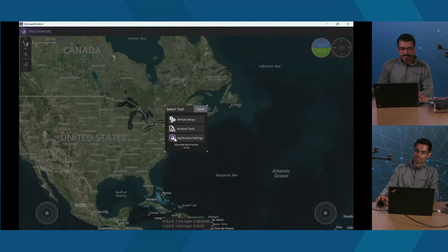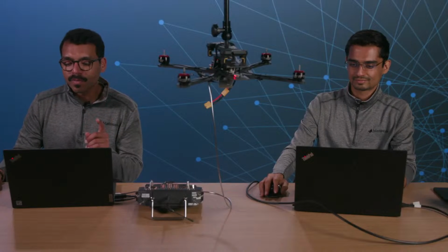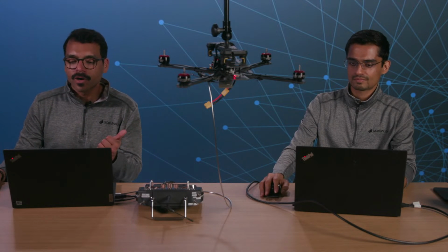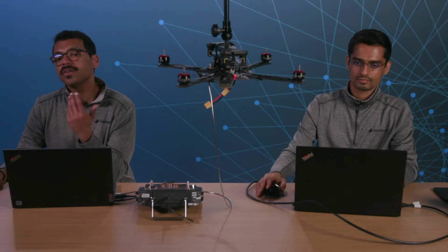Can we also use Mission Planner? That's a really good question. If you were going to work with Mission Planner, you can do that with ArduPilot or PX4. Generally, people use that for ArduPilot. I personally haven't used Mission Planner for a couple of years now, but there should be no restriction. You might have to build out your own MAVLink client to connect to it.